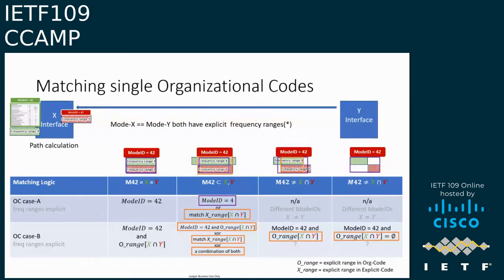So this is important information required by the path computation function, which makes use of the topology model, the optical impairment-aware topology model. We also defined, for example, for the ROADMs, power values for the drop ports. And so I think it's really important that this information is provided by the Yang model modeling the transceivers, in order to allow the path computation function to perform its job. So that was the rationale behind the current approach in the current Yang model.